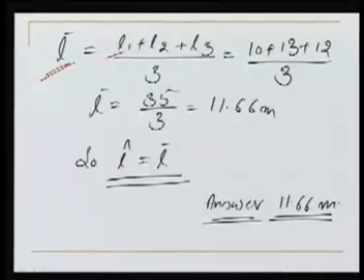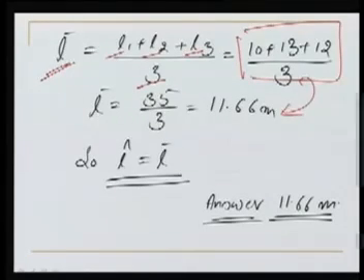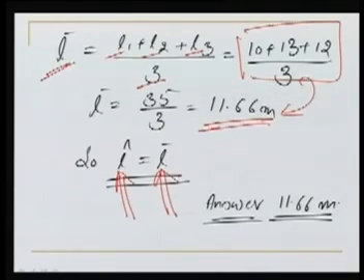So over here also, if I do the same thing, the arithmetic mean is L1, first observation, plus L2 and L3, divided by 3. So this particular value also comes out to be the same. So this also again we are proving here. What we found from the least square adjustment is same as the arithmetic mean.